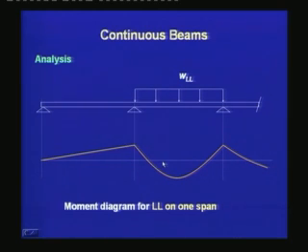But if there is live load only in one span, then it can create negative moments throughout the end span region. This type of conditions have to be considered in developing the envelope moment diagram.